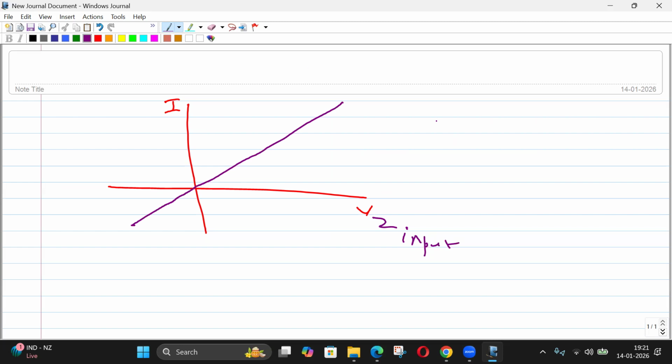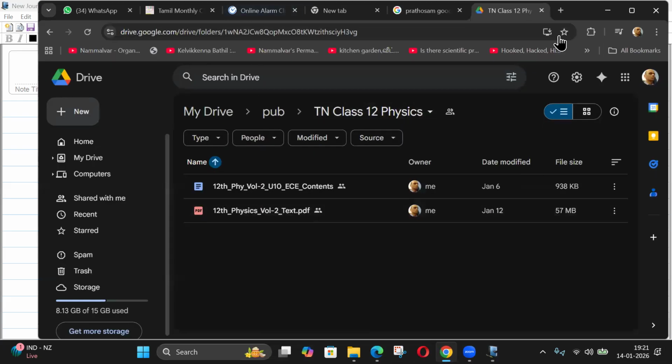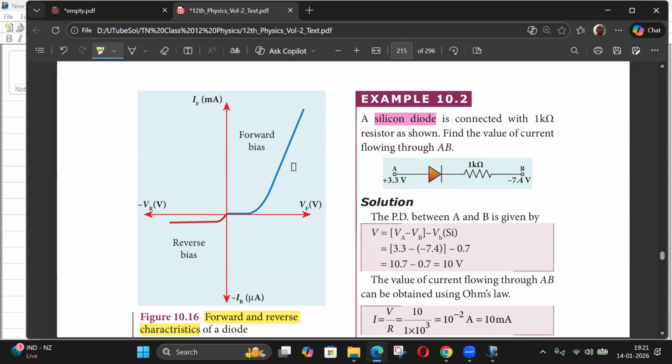Similarly for a diode, if you have to give a VA characteristic, the thing to notice is the forward voltage is in volts, reverse also in volts, but the current in the forward direction is milliamps, while in the reverse direction it's micro.